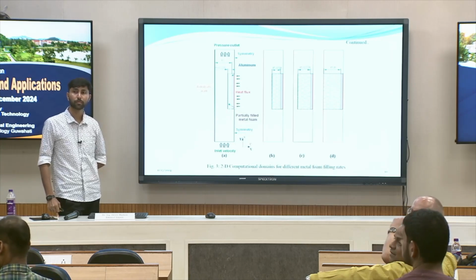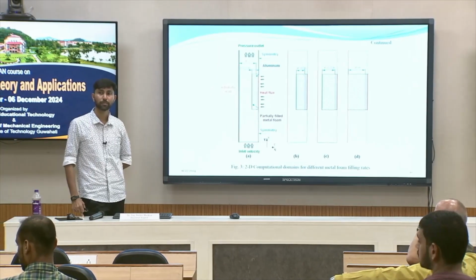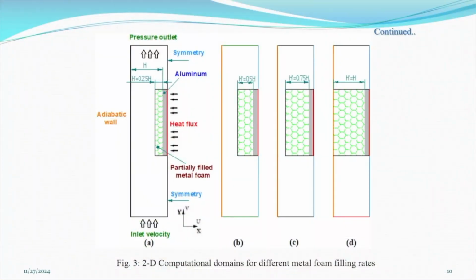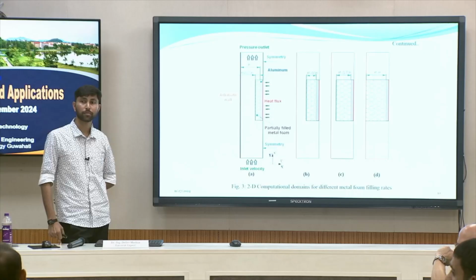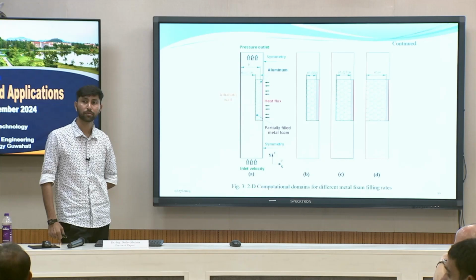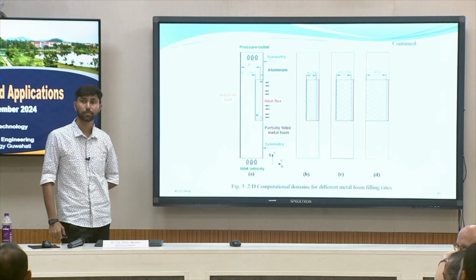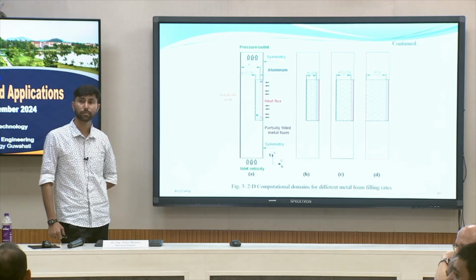Because in the porous radiant burner, the flame moves through the holes. So here also the air should move through the holes. But here, as per the structure, it is not moving through the holes, as it is a two-dimensional analysis. That is why the restrictions are more. Air is not flowing through it. Otherwise, if it had been a 3D analysis, then the structures would not oppose the flow much, and it might have allowed the air to flow through those structures, through the holes. But here it is indicating that the boundaries are opposing the flow.